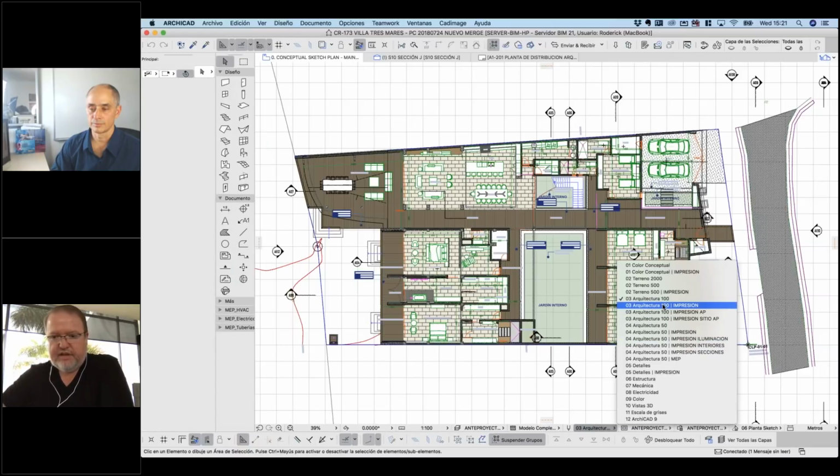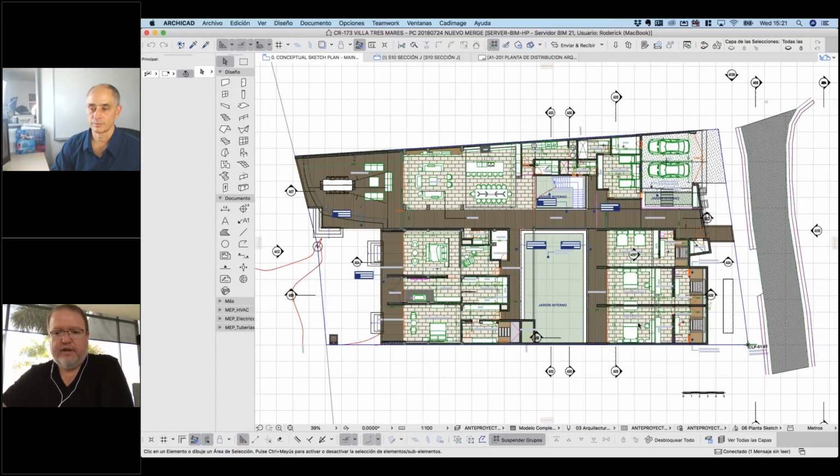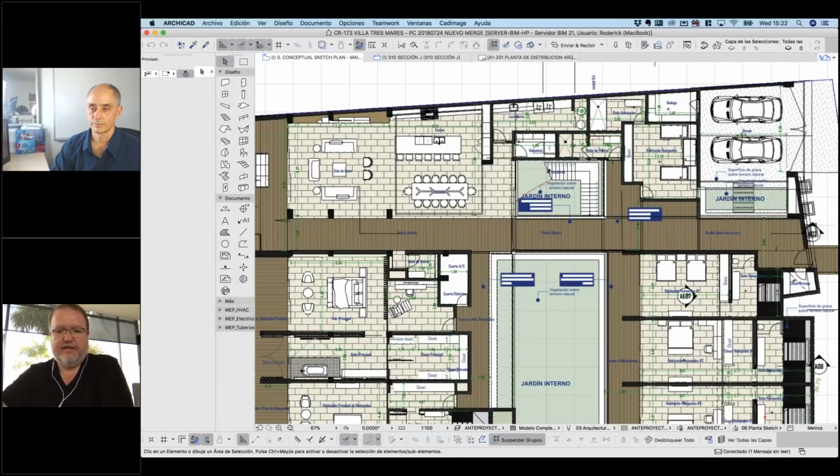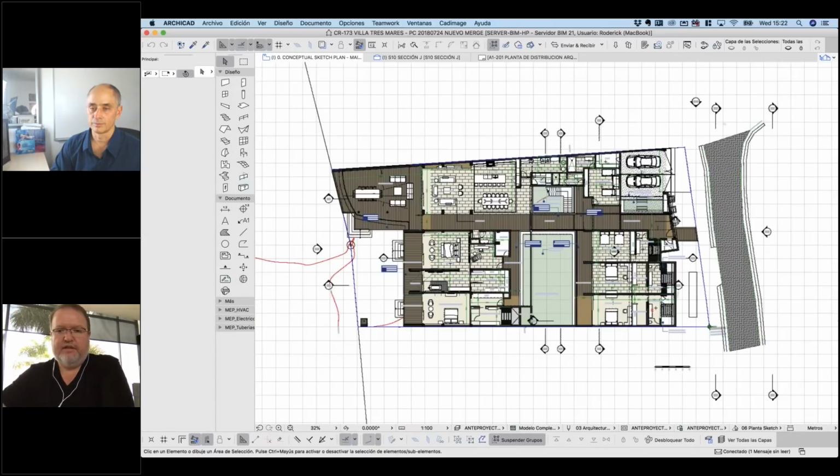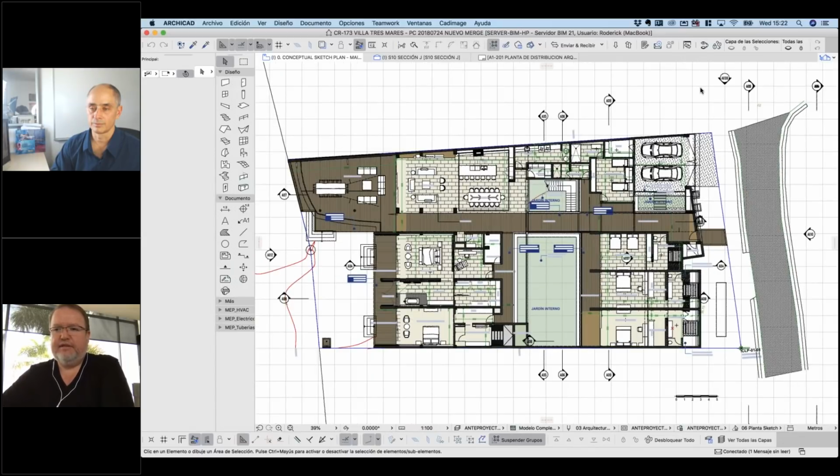And if I were to say, all right, how does this look when we actually print it or when we generate a PDF, I just end up applying a different pen set, which turns a lot of the stuff to black and just leaves the colors that correspond to those cover fills left on with the color, and maybe, for example, some of the annotations and that kind of thing. So that's one of the things that I've preset into the template.